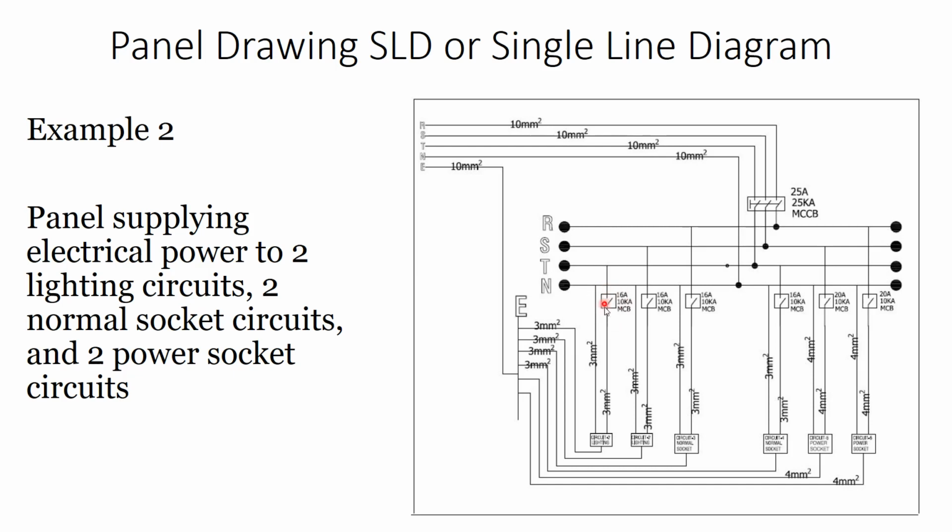And you can see here the miniature circuit breaker, which is used to protect each of these circuits. One for the phase itself and the other one for the neutral. Phase, neutral, and so on. So why do we do this? Why R, then S, then T, then R, S, then T? Because we are trying to reduce the unbalance between circuits. We have to reduce the unbalance as much as possible.